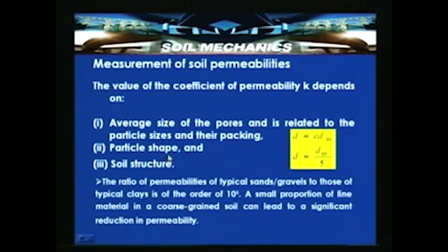In a single grained structure of bulky particles, there are two extremes, loose arrangement and dense arrangement, while in a natural arrangement it can be medium dense or very dense. Depending upon the arrangement, it has an effect on the permeability. For fine grained soils, the structure depends upon the physico-chemical environment surrounding the particles, and that can influence the permeability value to a large extent.